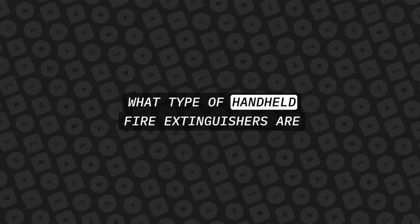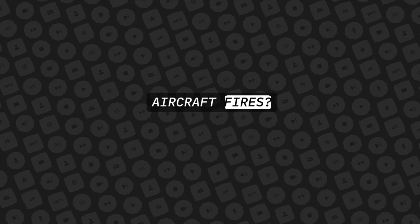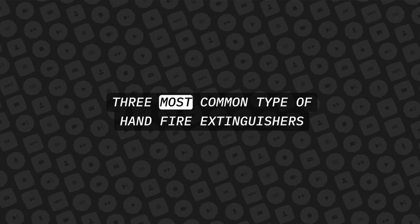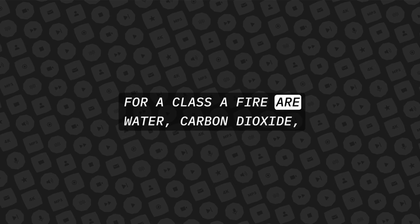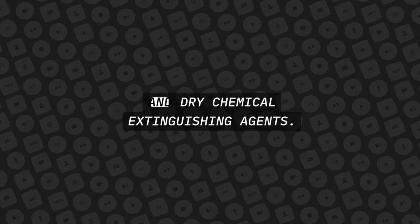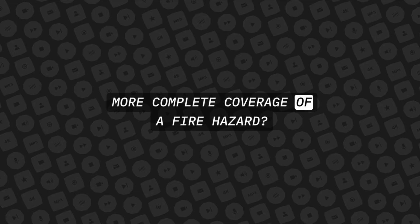What type of handheld fire extinguishers are available for extinguishing interior aircraft fires? The three most common type of hand fire extinguishers for a Class A fire are water, carbon dioxide, and dry chemical extinguishing agents. What type of fire detection system gives a more complete coverage of a fire hazard?